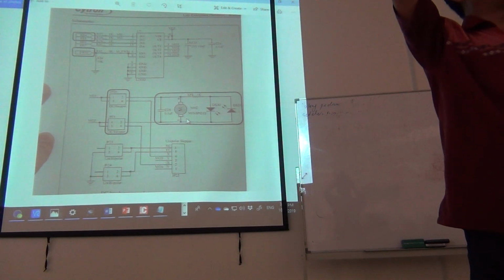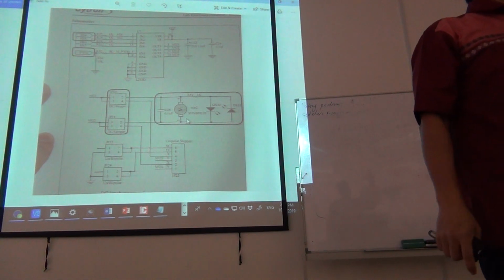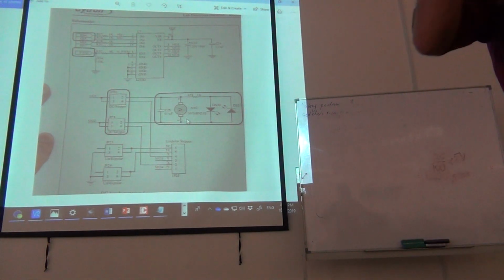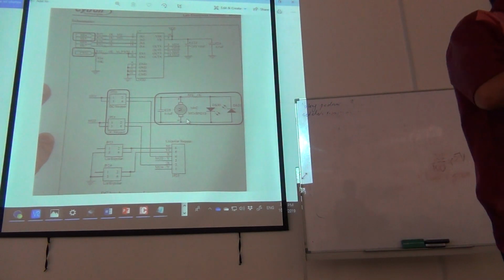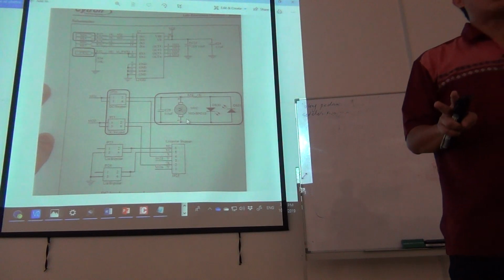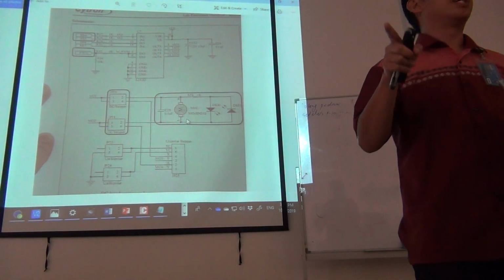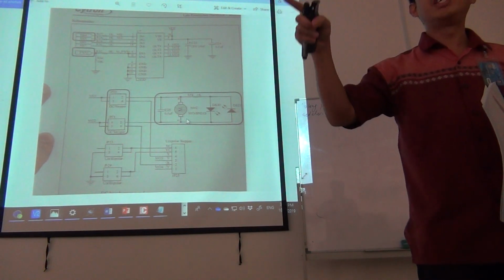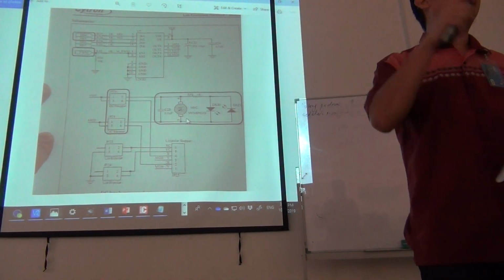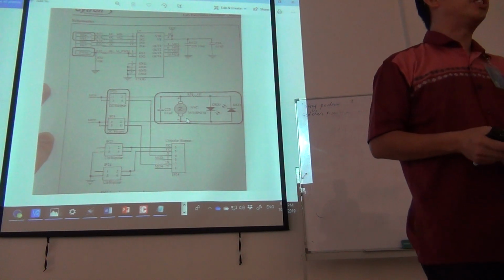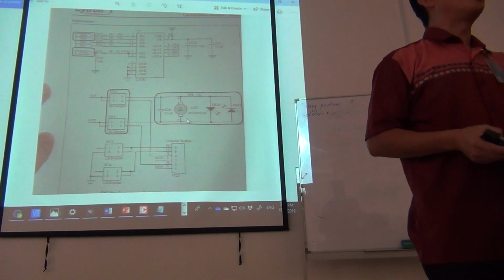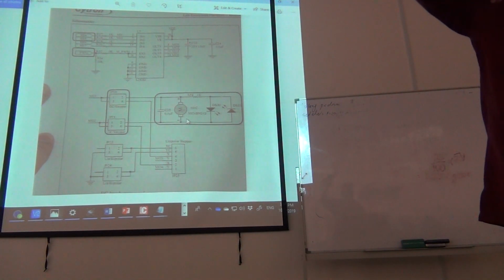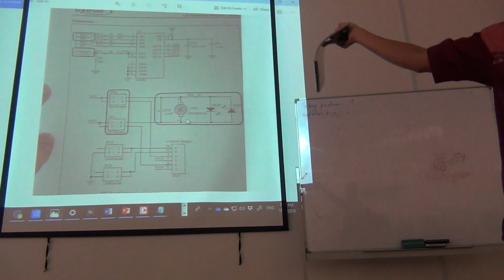What is inside here? The book is telling you the design of the board. The board is hardwired, meaning everything is hard-coded, and I cannot change the design anymore. For example, port D is all connected to the LEDs from pin 0 to pin 7, already on the board. I cannot change it anymore. So after you know how it works and how the design looks, you should be able to program it accordingly to the design.